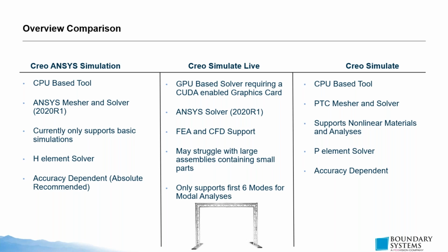The next tool, another newer tool released a few years ago, is Creo Simulate Live. This is another tool that comes from an ANSYS collaboration with PTC. The big thing to note is that it is a GPU-based solver, so it requires a CUDA-enabled graphics card. It's not just CPU-based. It does use the ANSYS solver, again 2020 R1.